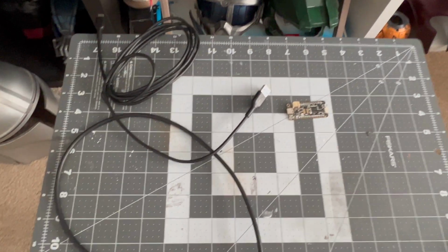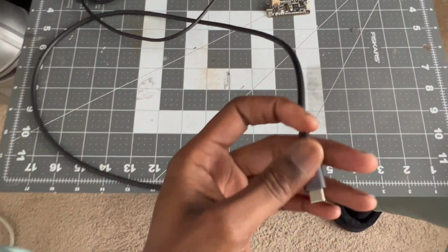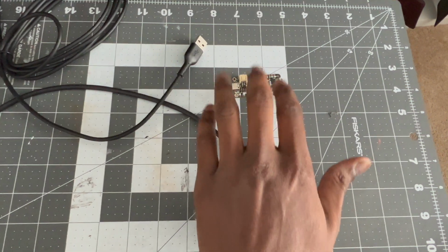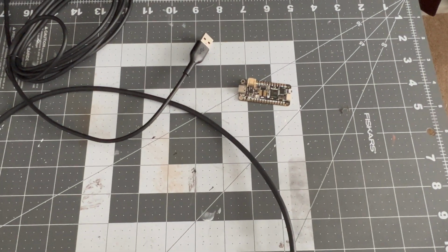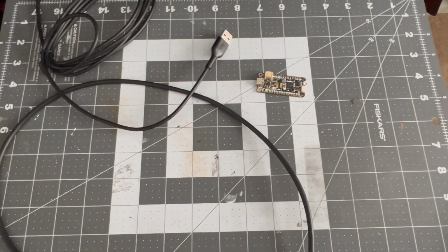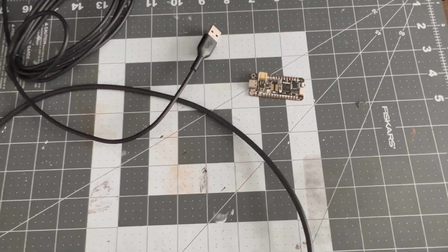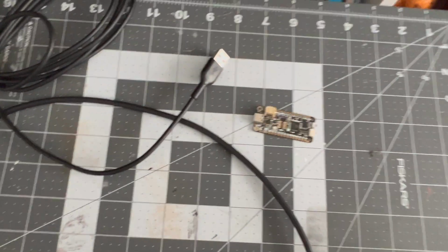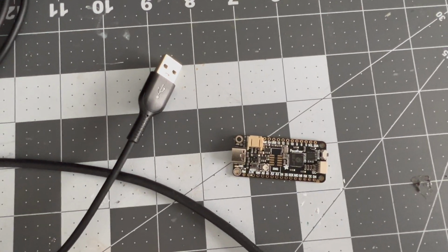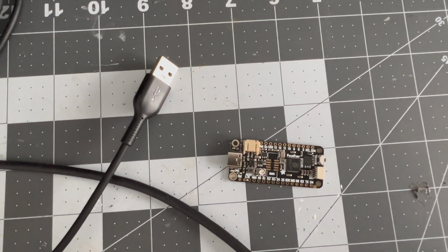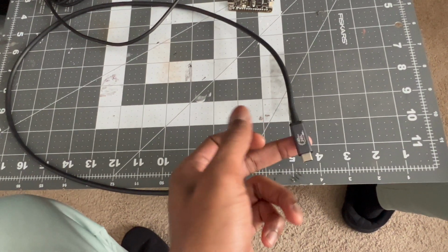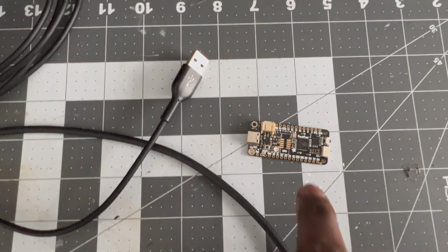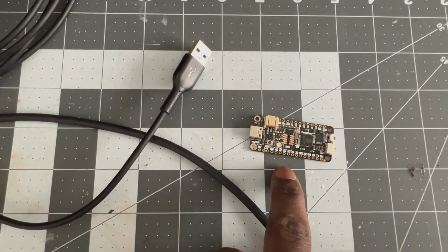Reason number two is a little bit more uncommon, but you may not have a USB data transfer cable. So you may have a USB cable to connect your Pi board to your computer, but it might not have a data line for you to send the code through. Some of these cords are primarily focused on charging. Some of these have data lines as well, just like we said with the light, how we have the 5-volt, the DIN, and the ground. So just make sure that you have the correct USB. Don't go crazy over it. A lot of them do have it, but that could be one of your problems. Primarily, like I said, start with the bootloader mode first.